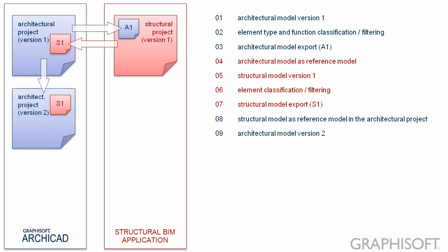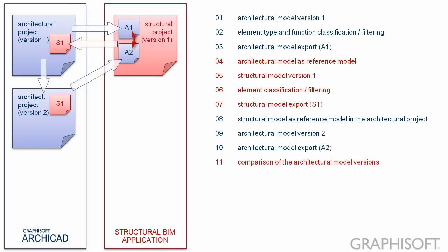9. Architects modify or update their project according to the imported reference model. 10. They export a new IFC file based on the project's new status. 11. The new architectural model is imported to the current structural environment as a new version of the reference model. It's compared with the old reference model version. The differences are displayed as new, deleted, and changed elements.